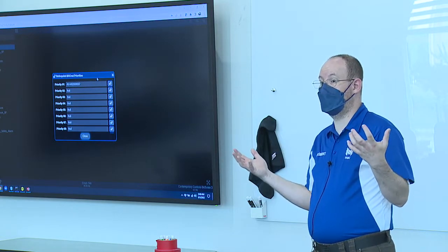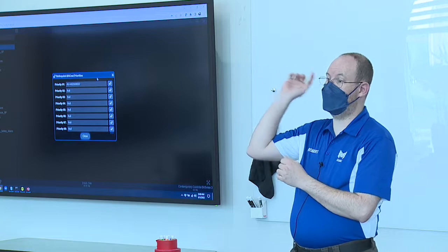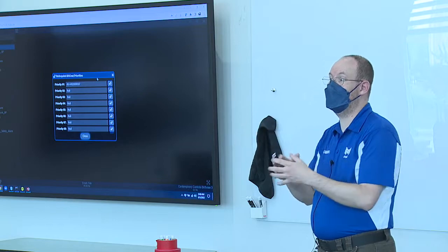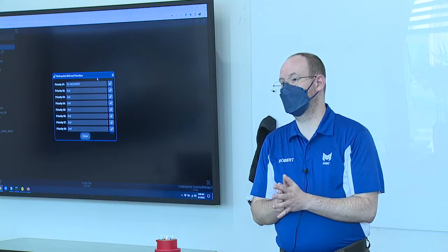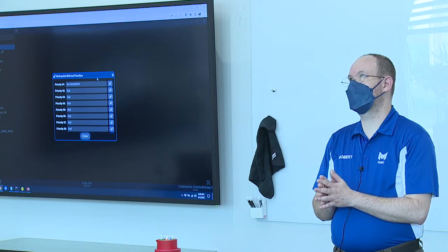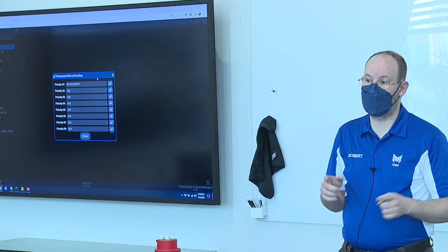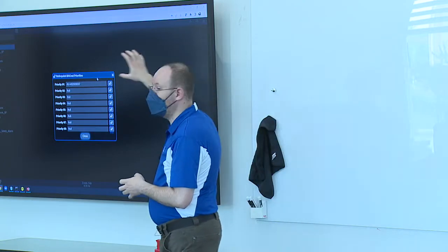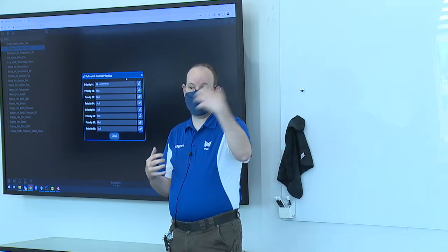Writable and read-only are flags that can be set on each BACnet point. But that's going to be set at the server end, on the controller that has that data. So it's a tag that's related to the data point on the controller, not a flag that lives on the device. The tag is associated with that data point. So when I create the discharge air data point in that controller as a BACnet point, I have the ability to make it read-only or writable.